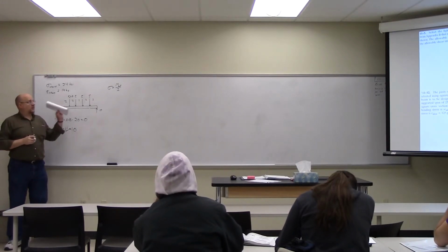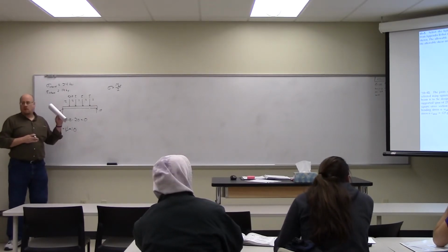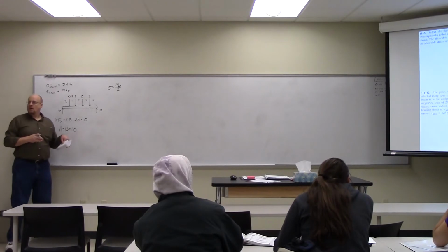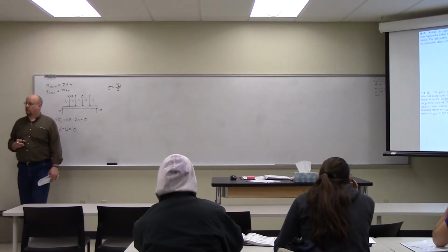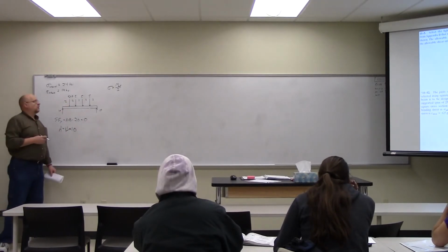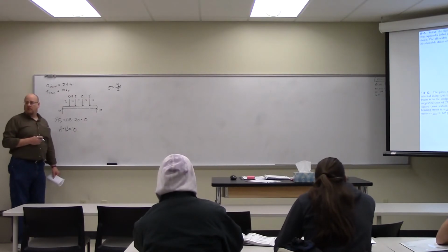Right, because Y is the same for the whole beam. It's a geometrical value, it's the dimensional value. Is that the entire height or just from the middle to the top? It's from the neutral axis, right? Well, and I is universal for the whole beam. So Y and I are geometrical figures, so we just need to find M max.